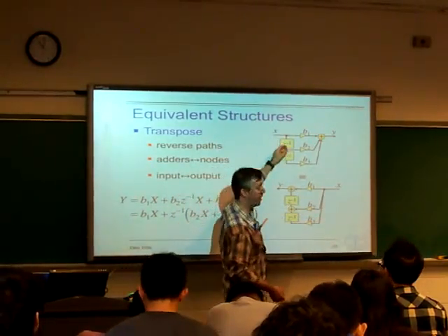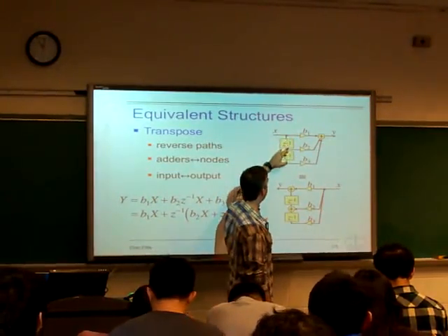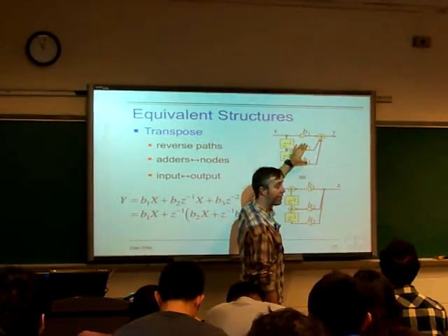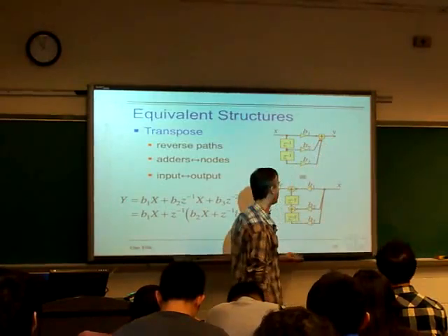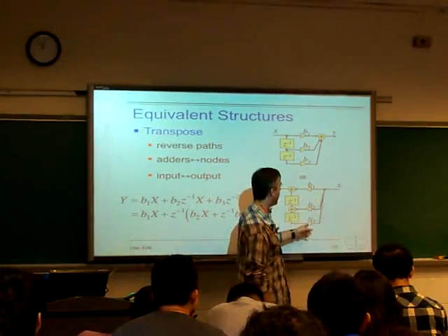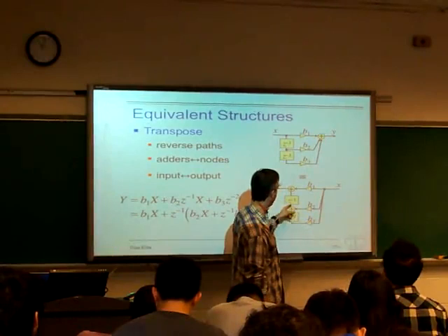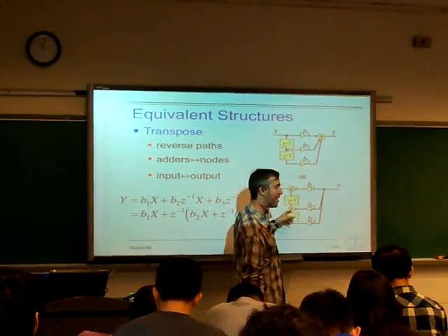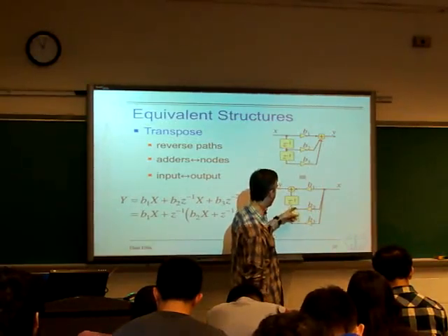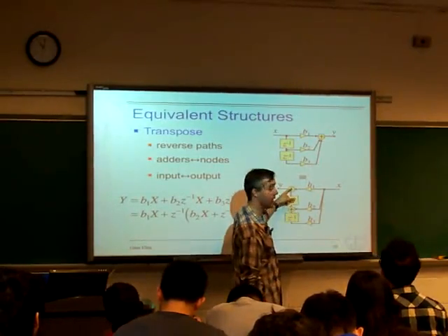Right here, if we follow through what it's saying we do, it's saying we take X, we delay it by a couple of steps, and then we take each of those delayed versions, multiply them by different gain constants, and sum up the result. This system here says we take the input X, we immediately multiply it by the 3 gains, and then we feed these into this sort of accumulation forward delay line, and then we add that into the previous delayed output of this, then we take that partial sum and add it up here.